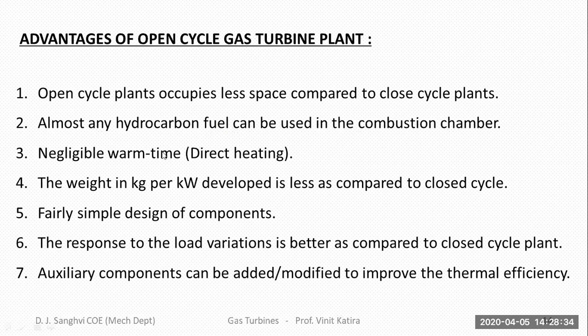Third point, negligible warm-up time. This is one of the major advantages for the open cycle gas turbine power plant, because the heat is directly added in the combustion chamber. The warm-up time is almost negligible. You can easily come to the rated power within minutes of starting.